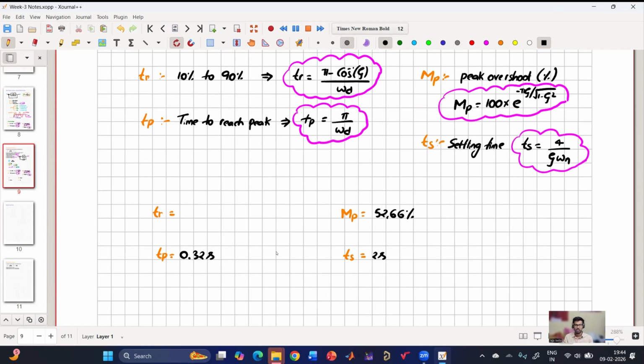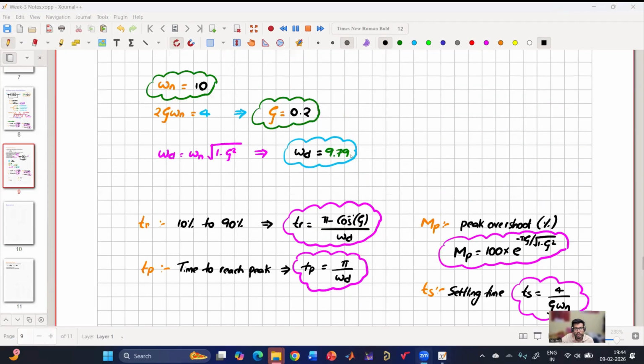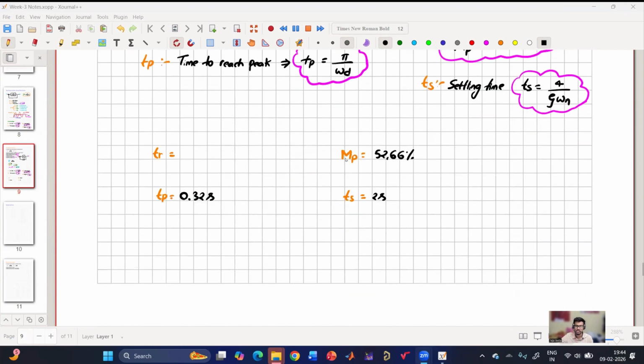Sir, can you tell me what is omega d? Sorry, your voice is very low. I can't hear anything. Sir, omega d. May I know the value of omega d or formula? Yes. Omega d is square root of 1 minus zeta square into omega n, and omega d is 9.79. Okay, sir. So can you get anything from this? If someone does it, please let me know the rise time. Then we can solve.